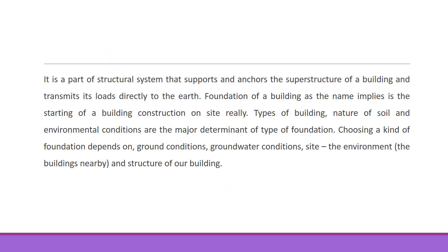What is foundation? It is a part of the structural system that supports and anchors the superstructure of a building and transmits load directly to the earth. Foundation of a building, as the name implies, is the starting point of the building. Type of building, nature of soil, and environmental condition are the major determinants of the type of foundation. Choosing a kind of foundation depends first on ground condition, groundwater condition, site, the environment, what buildings are nearby, and the structure of our building.